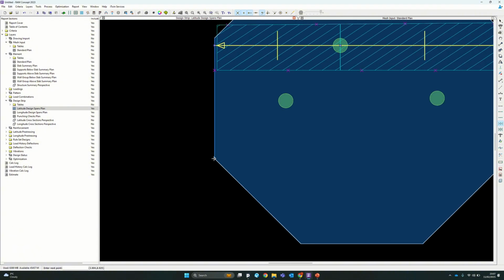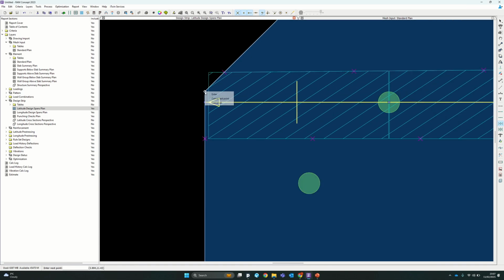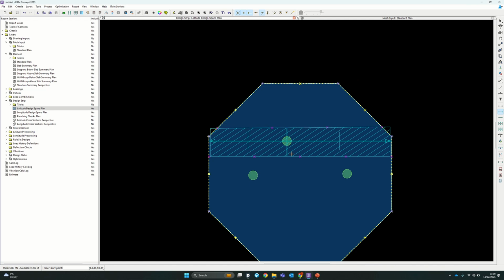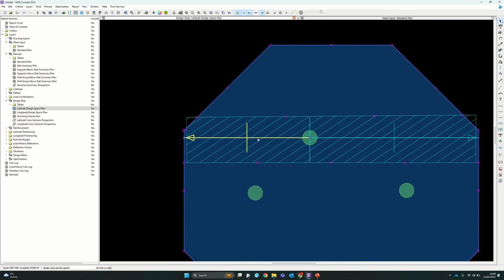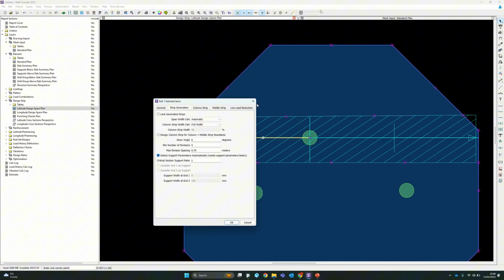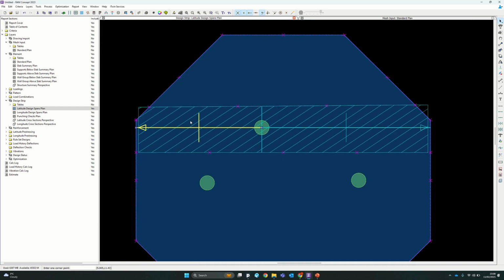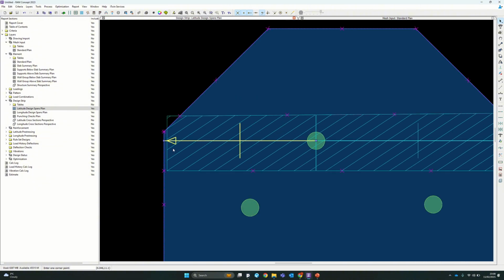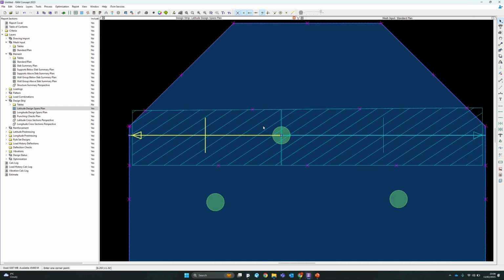Because these design segments, is that what they're called? Just trying to highlight it. Yeah, span segments. Span segments are what is then used in the design analysis stepping to give you your results. And when you go to display these results across the slab to get the slab forces, it will just give you whatever shear and bending is within each span. So effectively they're like beam strips, and it will design it like beams.